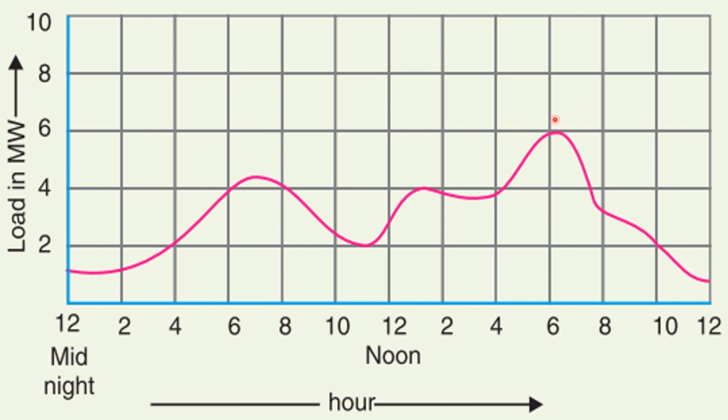The average load may be taken from this load curve, and you can calculate the area under the curve and divide it by the number of hours in a day to get the average load in megawatts. For that you need the equation for this curve, which is being shown here. That is a complicated curve. Another simplified method, which is just an approximation, is to sample and hold.